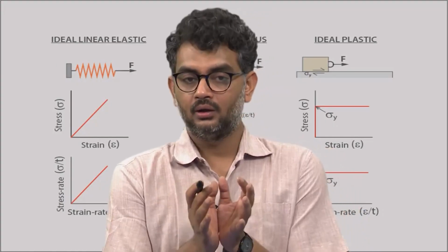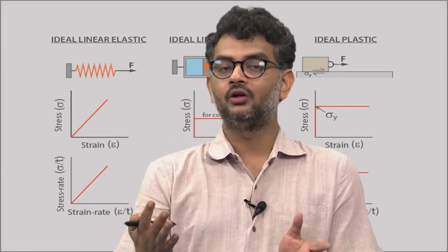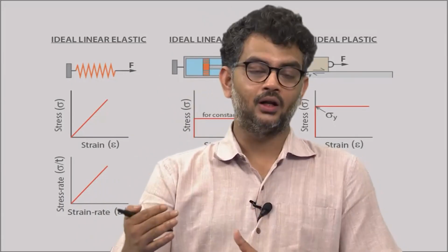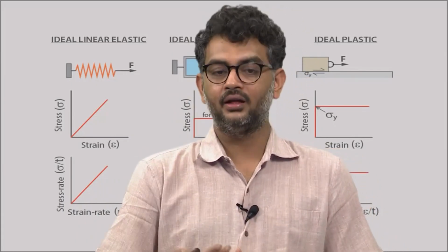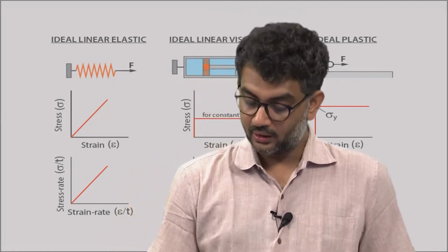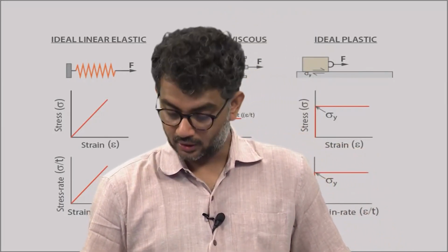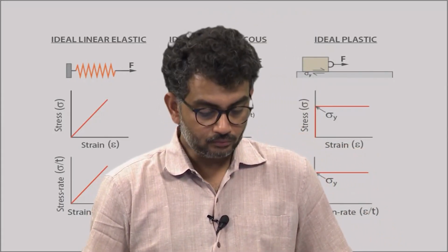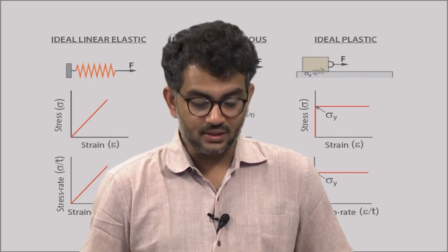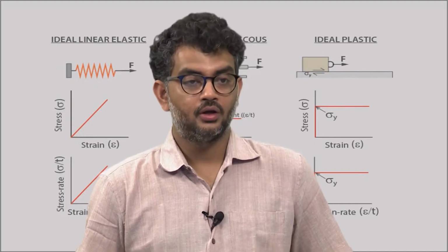You remember the mean stress and all other issues. And when we are not dealing with the normal components, that means the off-diagonal components where shear stresses are acting, then simply by considering i not equal to j, you can get the shear modulus of the elastic material. Now, with this I would stop, and then we will move to the next topic, viscous rheology.